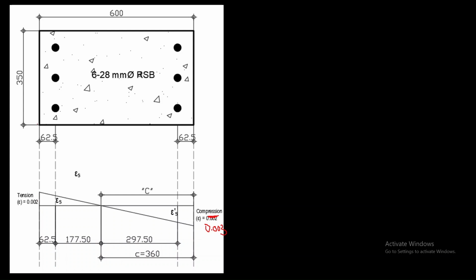After projecting the outer edge of this section and their reinforcing steel bar, this is the strain of steel reinforcement for the tension side and the strain of steel reinforcement on the compression side. Since the strain is in terms of a triangular diagram, we project these values to this and connect those points, and we get this kind of illustration.